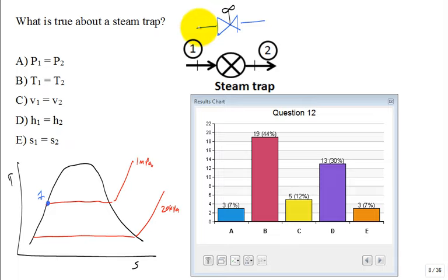Yeah, you get a pressure drop, but it's not reversible, is it? It's irreversible, which means entropy goes way up. That means that the entropy at 1, there's no way that it can do that. So how do we sketch it on a TS diagram? Out to some higher entropy at the exit. Why do I put a dashed line instead of a solid line? Well, that's the convention used in many textbooks and many parts of thermodynamics to indicate a process is irreversible. It's kind of going from state 1 to state 2. We don't know the exact path. It's a dashed line. It's irreversible.